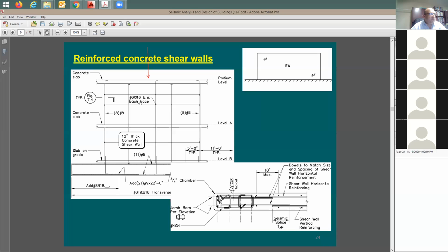But sometimes these walls are also exposed to lateral forces coming from the seismic. So for example, you come here, they say earthquake forces are going to be coming this way, and maybe also at this level coming this way, right? This creates a moment because the structure system is like a cantilever system. You see this? Just consider it to be like a cantilever system, if you like to model it. So this is going to be fixed here at the bottom. Total moment is going to be equal to this force times this height, plus this force times that height. You're going to have a good moment here. The moment is going to be big when it comes to concrete shear walls, and the moment is going to be acting this way, which means causing compression here and tension here.